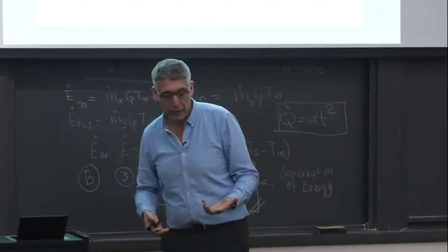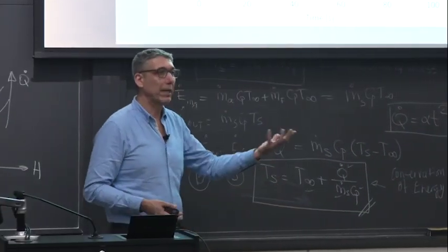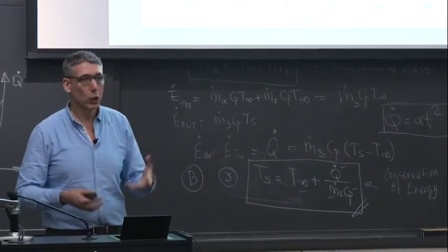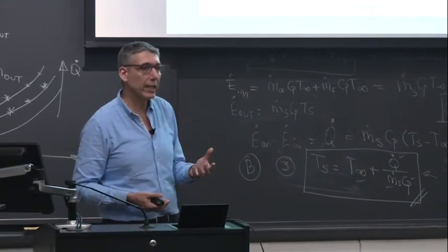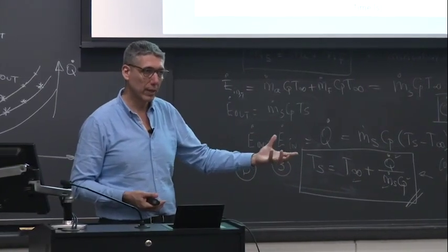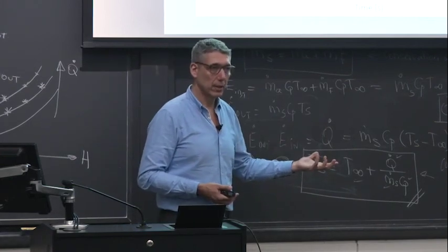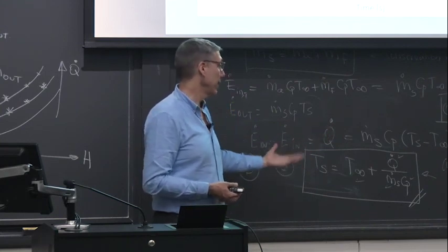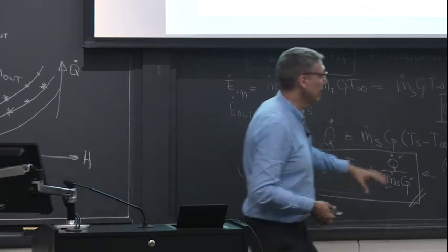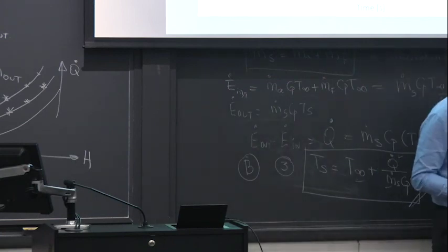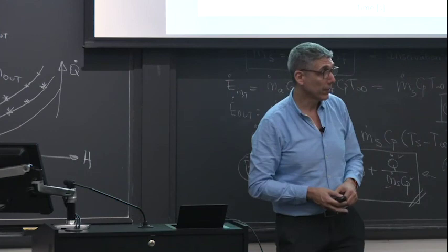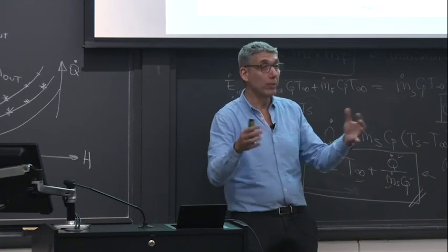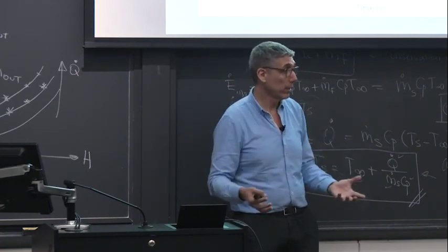But given that what we're trying to achieve is purely being able to compare this time to flashover with the egress time, then this particular solution becomes good enough. Okay? So as you can see, it's a pretty simple and straightforward approach that is based on very basic principles of fluid mechanics, where in reality, we are just simply doing an energy balance, a mass balance, and doing a little bit of a trick of fluid mechanics to come up with an empirical correlation for the air entrainment. We combine that with experiments, and that way we have circumvented completely the problem of having to numerically solve the entrainment function on a pool fire.